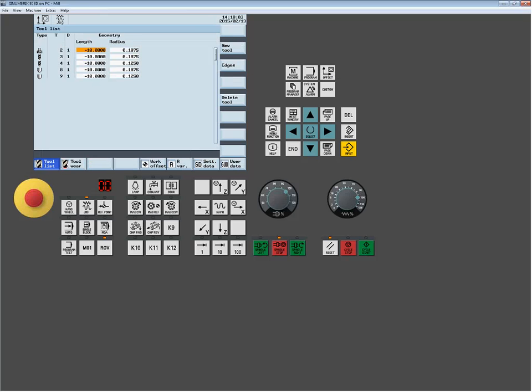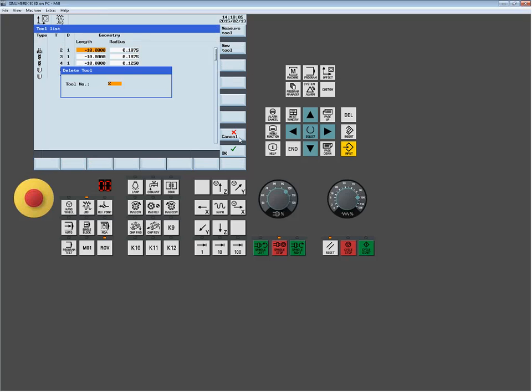So what this cheat code right here is doing is it's actually prefetching the carousel for the next tool. Unfortunately, this machine that we happen to be on is a carousel tool changer, meaning I can't randomly set up my tools. Well, you're going to find that depending on how they commission the machine, this can create some interesting results.